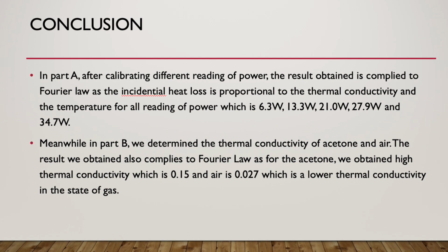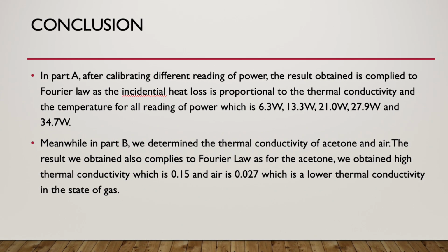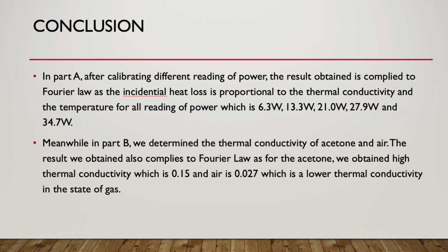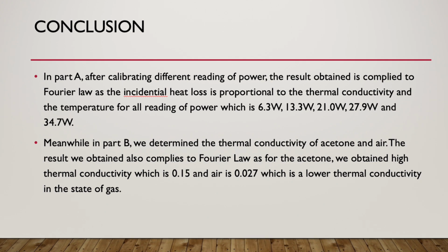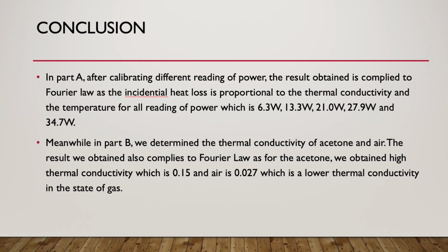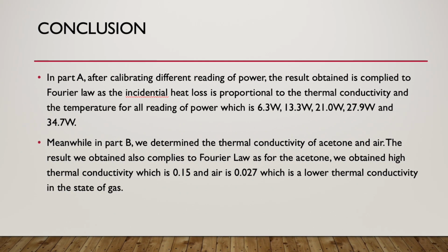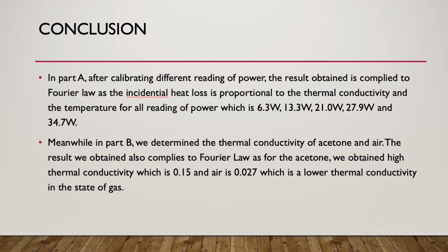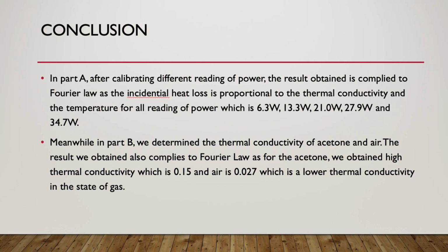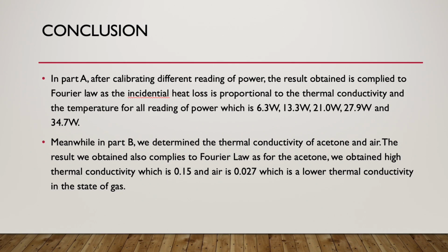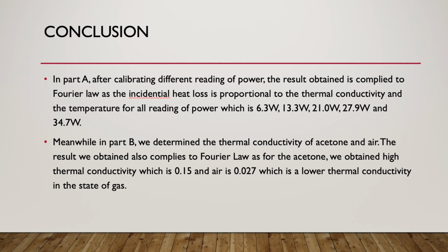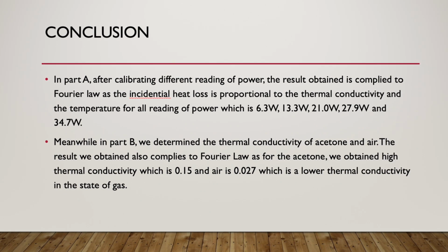In the first part, after calibrating the different readings of power, which are 6.3 watt, 13.3 watt, 21 watt, 27.9 watt, and 34.7 watt, the result we obtained is near to Fourier's law theory, as the incidental heat loss is proportional to the conductivity of the gas and the temperature. As the power supply increases, the temperature of the apparatus increases and leads to an increase of the thermal conductivity of the gas. The calculated percentage error is less than 10%, hence the result of part A is accepted.